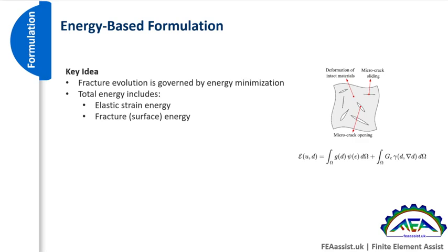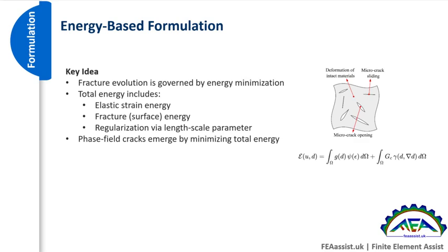The minimization of these two energies, the fracture or surface energy and elastic energy, will help us to regularize the smooth transition. This regularization will be done by a length scale parameter. So phase field cracks emerge by minimizing total energy, and the length scale controls crack diffuseness.